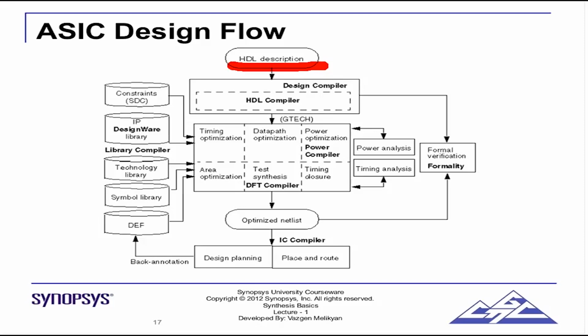This is again a separate, very big field called verification. That is, you make sure by using some test stimulus that the RTL code, the Verilog code, actually performs according to the functional expectations. Once we have made sure that the RTL is verified 100%, we go to synthesis. You could also use synthesis for design exploration. Obviously, you do not need it to be passing 100% verification. Many people do that. So we go to Design Compiler.